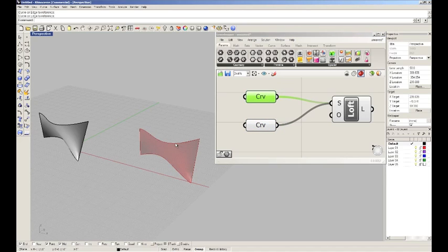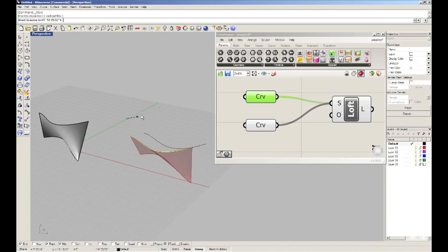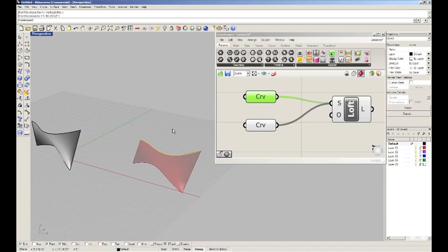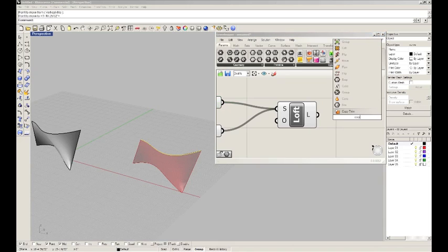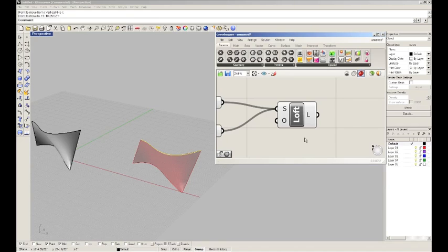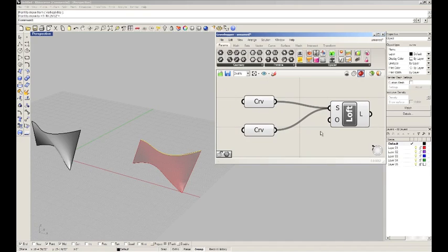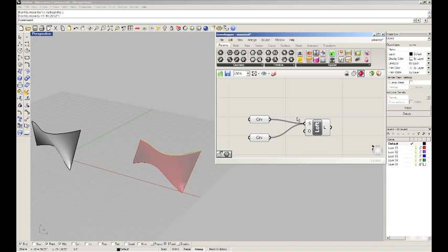Pretty simple. But what it does allow us to do is to have the same operability in Rhino that we had using the record history or the implicit history, but now it's explicit, right? We know what 2 curves, we can go in and identify what 2 curves are lofted together. We could also copy them. Well, let's skip that for now. It gets a little bit more complicated in Grasshopper, but you can do the same sequence of things, right? So you can control the order and the number of steps of things because you're mapping them out for yourself. Basically, you're making the history explicit rather than implicit.